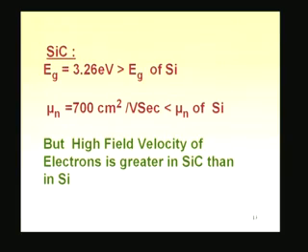Now, silicon germanium we will touch upon later, but silicon carbide is a material which is very vigorously looked into, because its band gap is larger than that of silicon. It does not get our nod today because of this property, mobility. It is smaller than that of silicon.